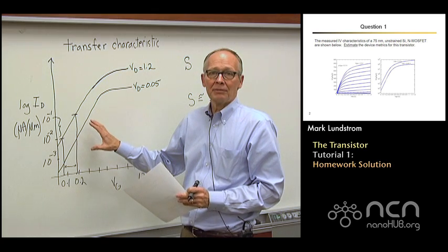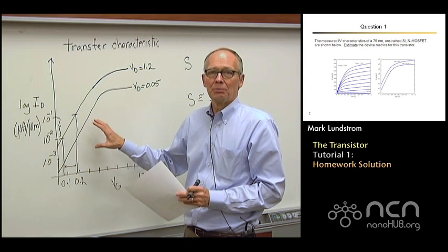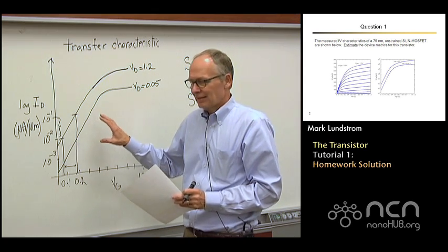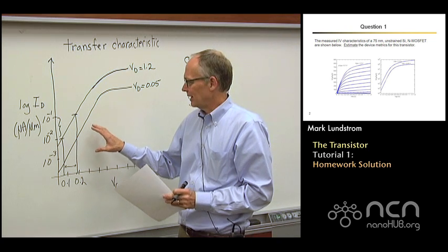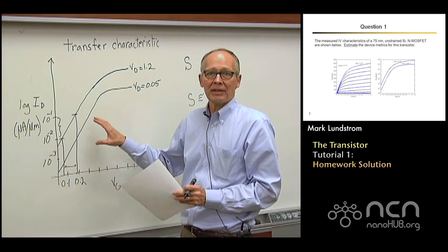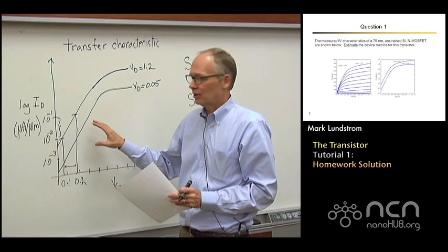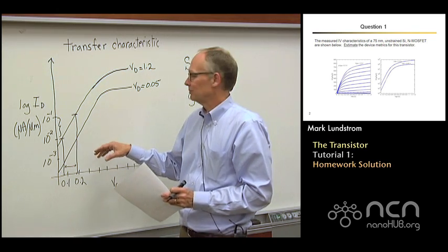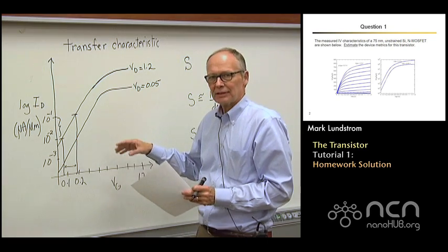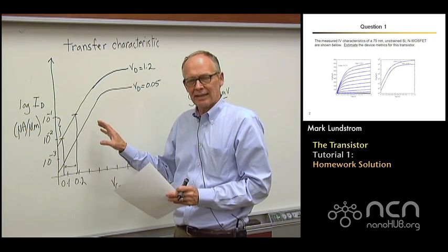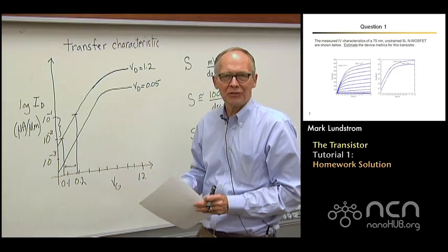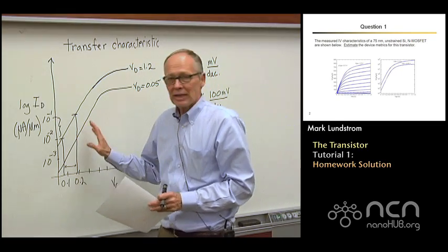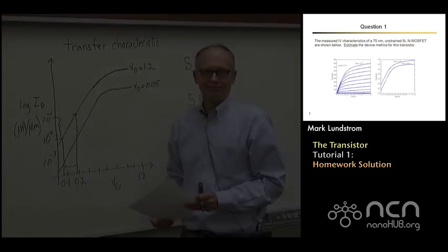There are many other device metrics that you can pull off of these curves. They're listed in the homework assignment, and the solutions go through some of them. It's good to familiarize yourself with how you extract on current, transconductance, off current, output conductance, and things like that, because we'll be talking about those concepts over and over. So that's it for problem 1.